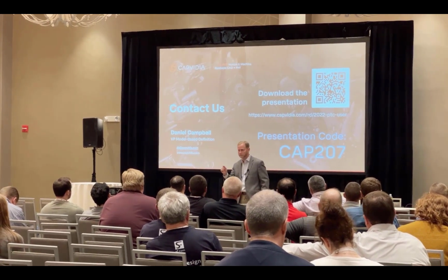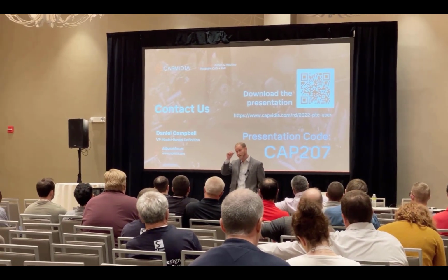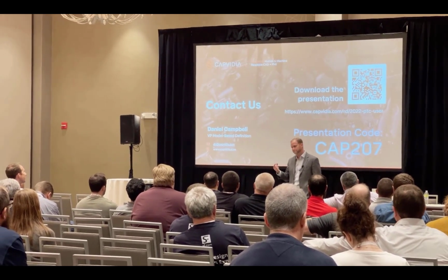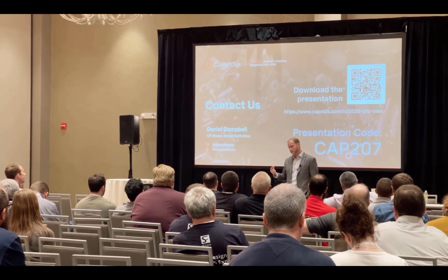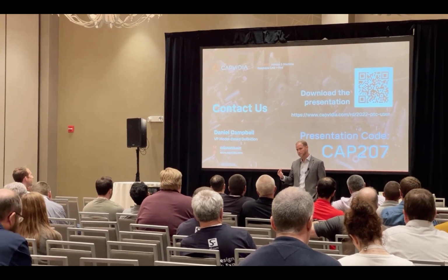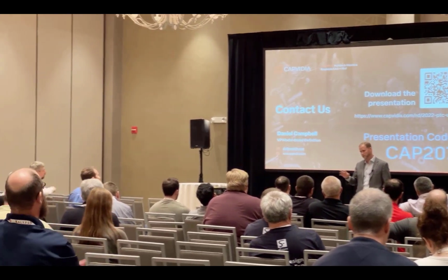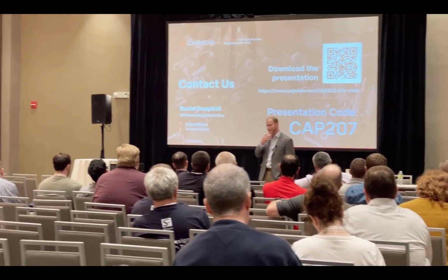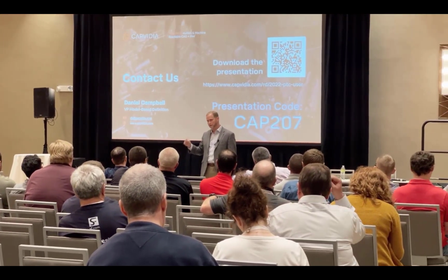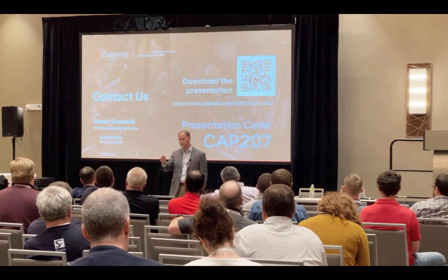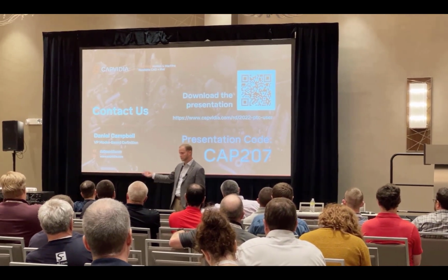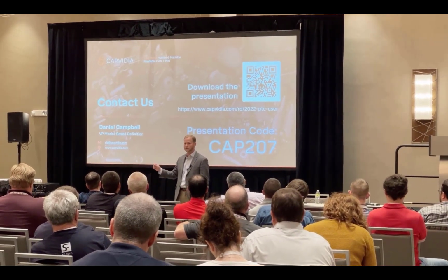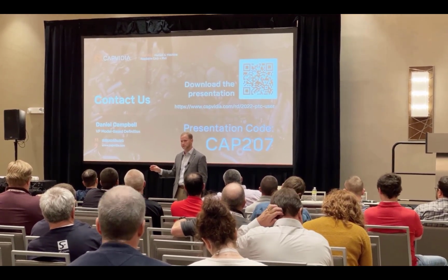For that, you'll have a one-to-one relationship between your QIF MBD and your Creo model. Then you might start to layer on other information. Let's look at the simpler case where we're starting to collect measurement result information. Typically, that will be stored as another instance file. So you'll have a QIF file in Windchill, and then you gather up a batch of results. You have a .QIF file that has these results.